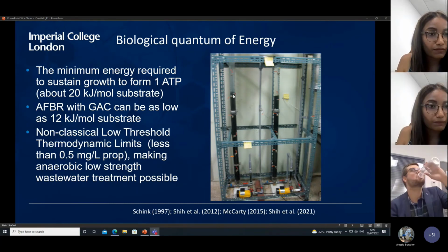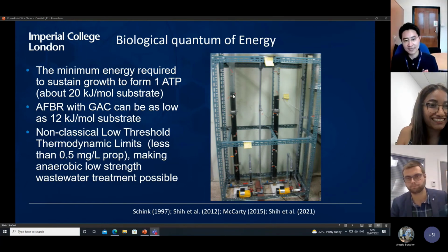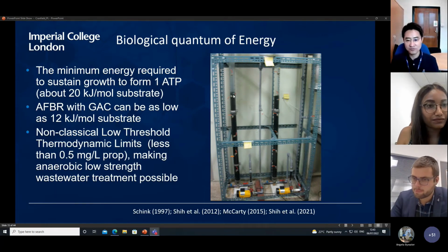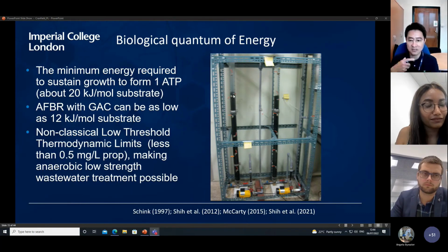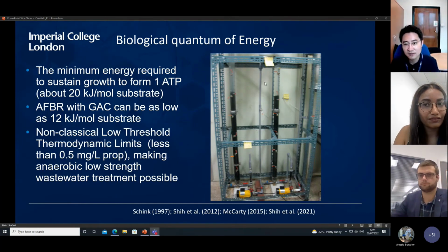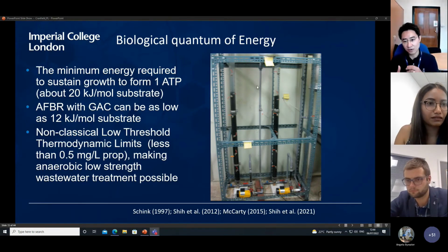Yeah, I forgot the brand name. I used to have it. It's from the States. It's not a special GAC, we just use it. Usually it's used for drinking water filtration. The size we use is about 2 millimeters to 4 millimeters. We don't use fluidization because we don't want to use a lot of energy, so we use more gentle mixing. You can see that the columns are very good, with very clear liquids. I also create a biofilm. The key, I think, is how you operate with gentle movements and create the biofilms. That is the difficult part. But GAC itself I don't see as quite challenging.